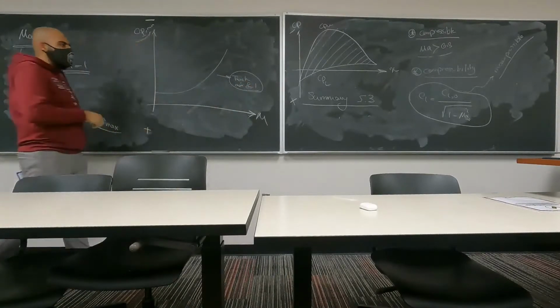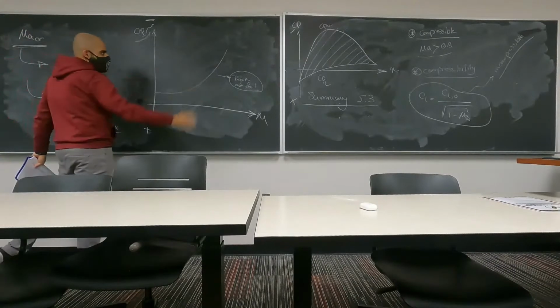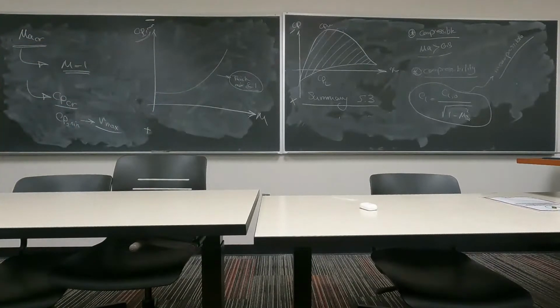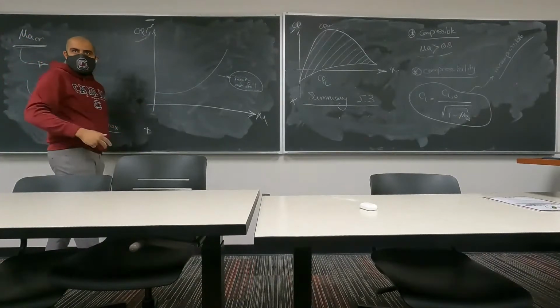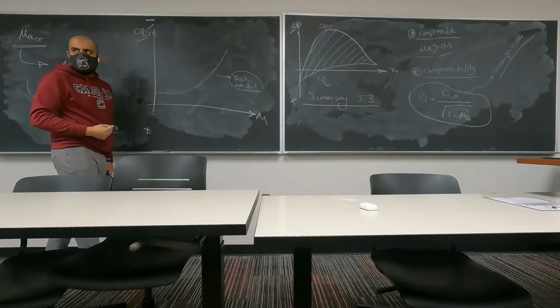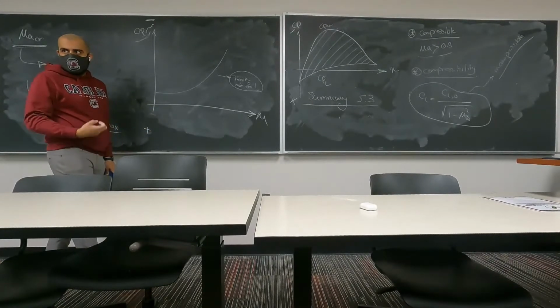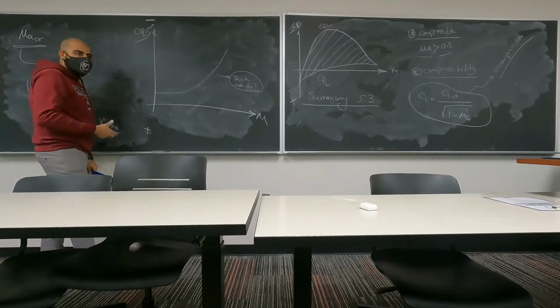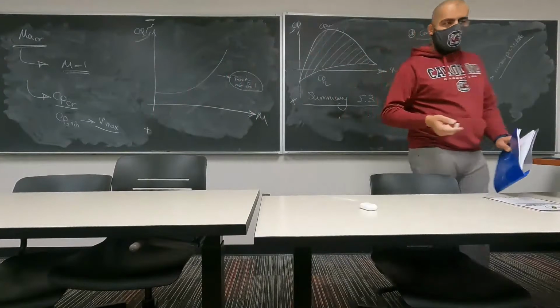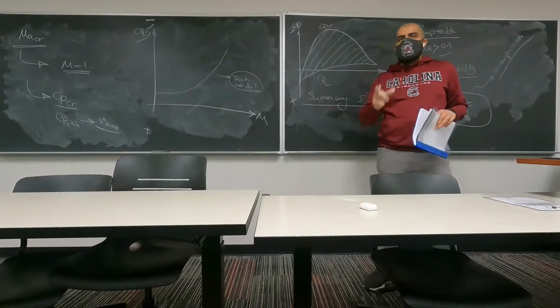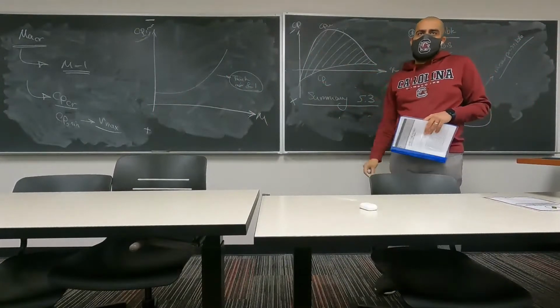How would this plot change if you are dealing with a thinner airfoil? Essentially, this shows the relationship between the pressure and velocity, right? The idea is as we increase the velocity, your pressure is going to decrease, right? That's the idea. So how does this relationship change when you decrease the thickness of your airfoil?